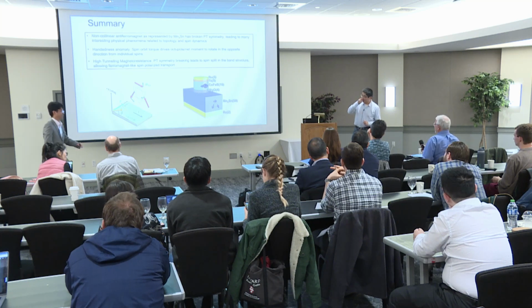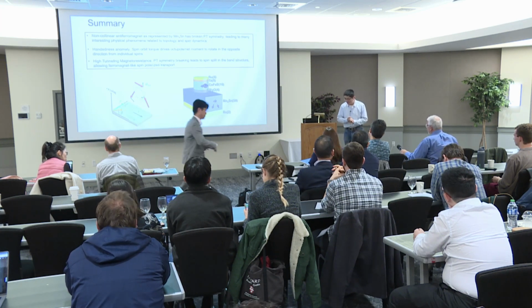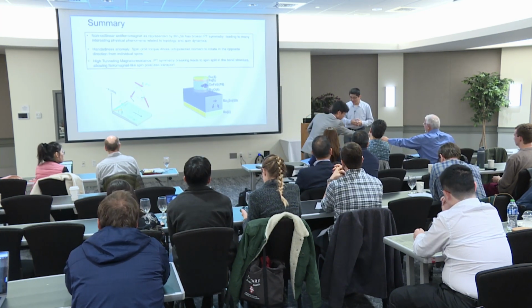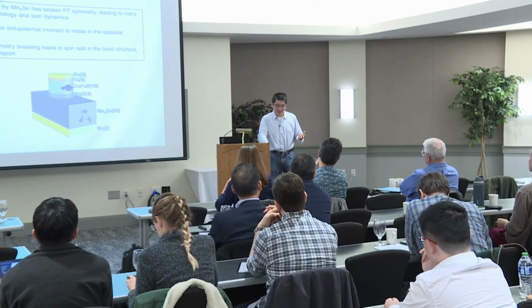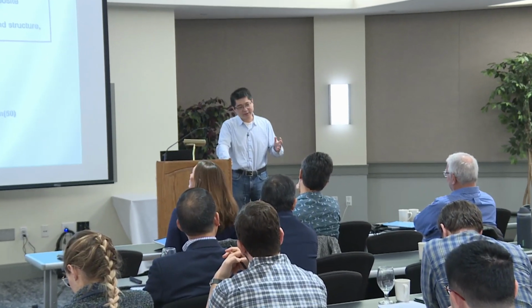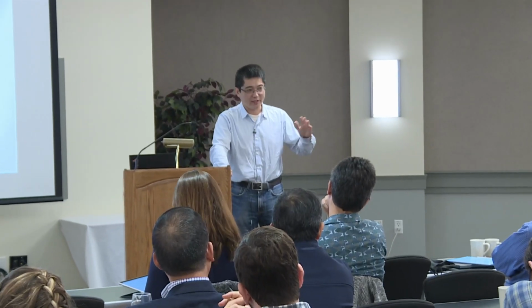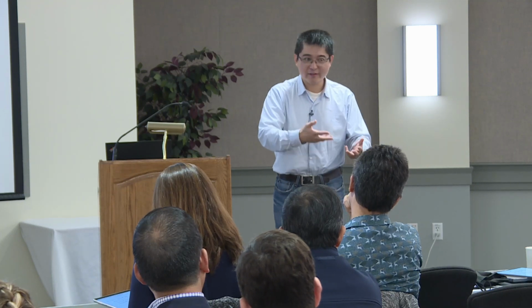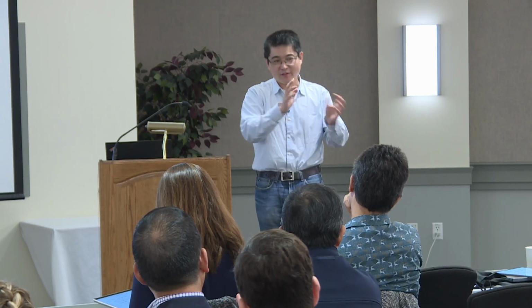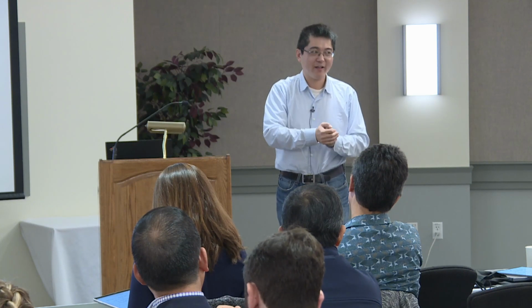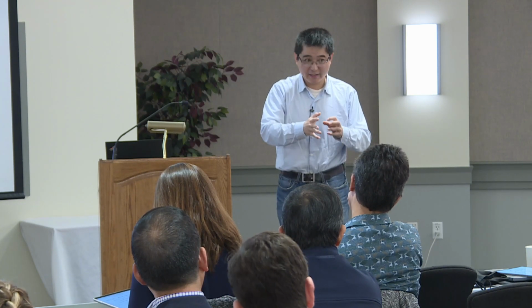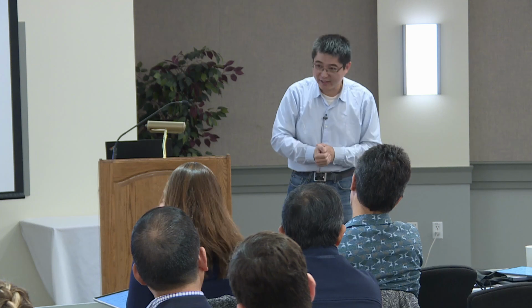Yeah, so for the first question, why don't we just utilize anomalous Hall resistance? Why do we want to develop a magnetic junction? The reason is, I think, so far the anomalous Hall resistance is still quite small, let's say in a few ohm range. Also, you probably need to make a 4-terminal device in order to do it. So in practice, circuit designers don't like that. MTJ is probably so far the only practical way to make memory or logic devices.